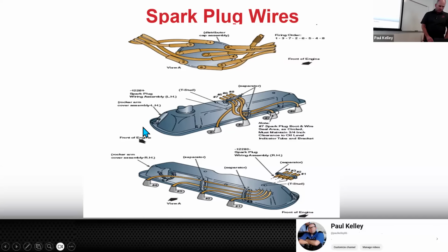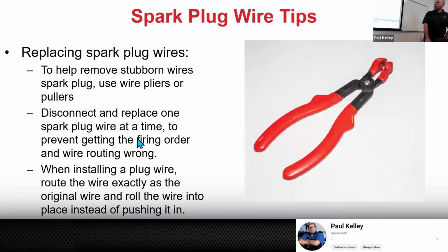Okay, cool. And then we go to replace them. You can usually pull on them, but if anybody's going to pull a spark plug wire today, I'm going to warn you right now. If you grab it by the wire and you yank on it, it's probably going to rip the wire out of the boot. And again, like normal, ask me how I know, but I think you already know. The mistakes you are going to make are the mistakes I already made. I just don't want to learn that lesson again. I've been enrolled in the School of Hard Knocks for long enough. I even lost my hair over it.